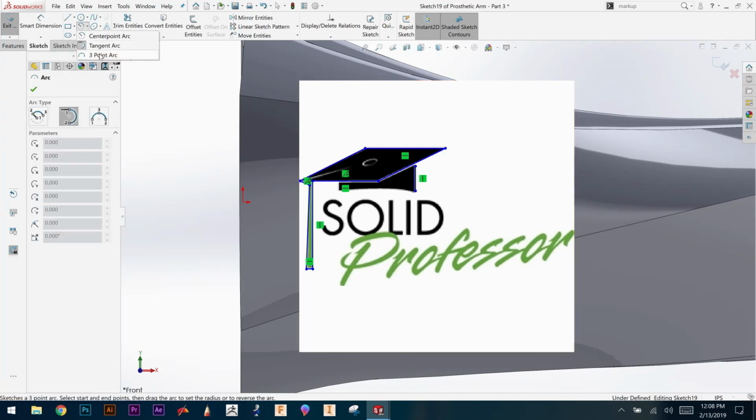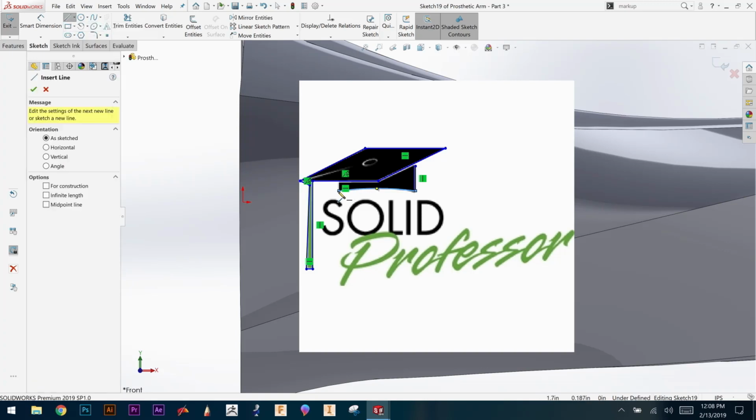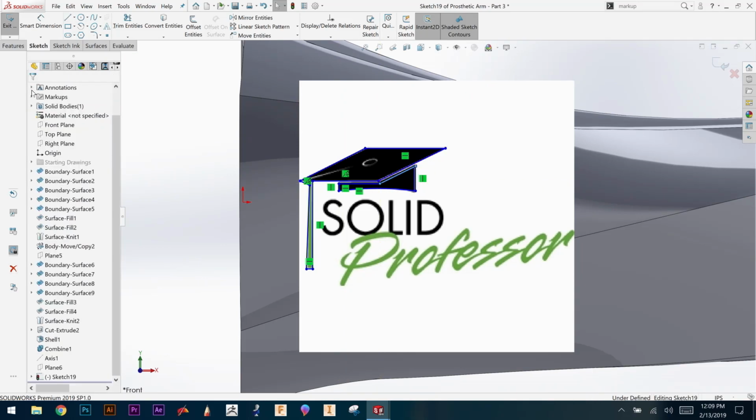Sorry, we need 3-point arc. So we'll connect these 2 points, set our arc, switch back to the line, and we're just finishing closing that off. So you can see it's pretty easy to draw right in that sketch and use the picture as the basis for creating a custom logo or popping something out of your model.